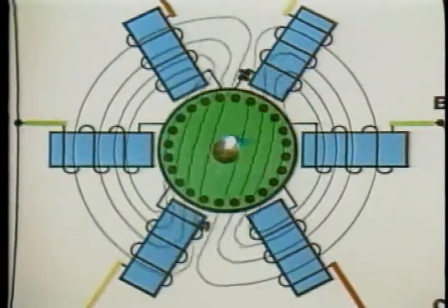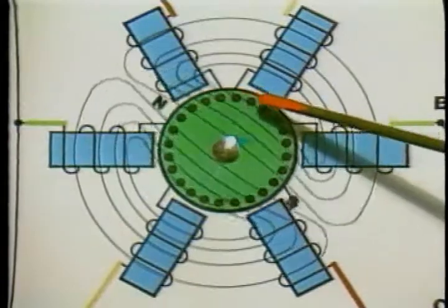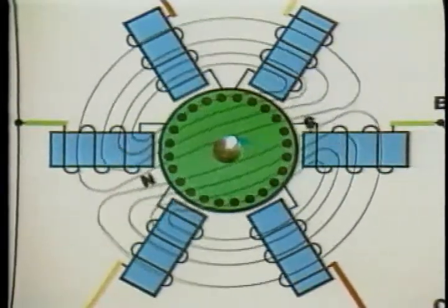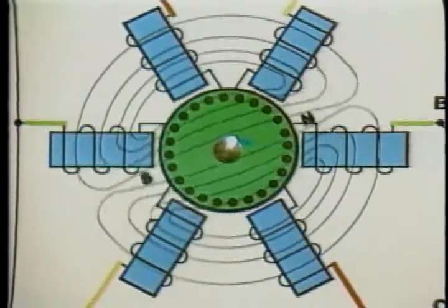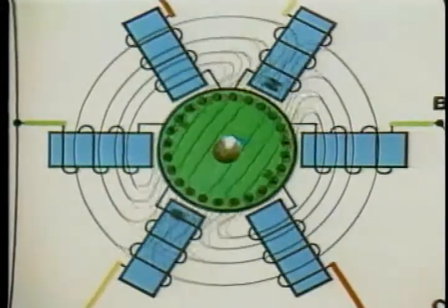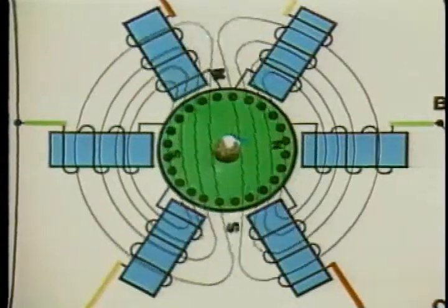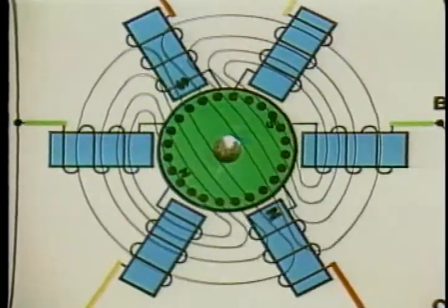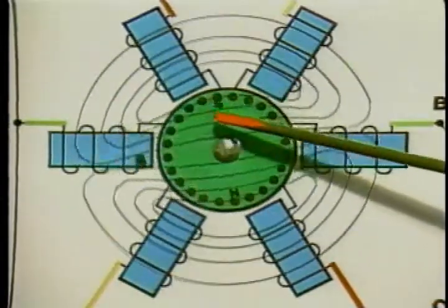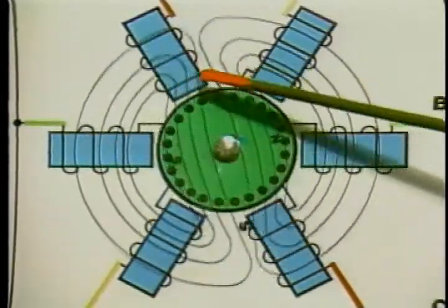The rotating flux lines sweep past the stationary rotor conductor bars rapidly and induce maximum voltage in them. Resistance is low and high currents flow in the conductors. These rotor currents produce strong rotor poles which follow around the motor between the stator poles. Each rotor pole is pushed by the stator pole behind it and pulled by the stator pole ahead of it, so the motor exerts torque.